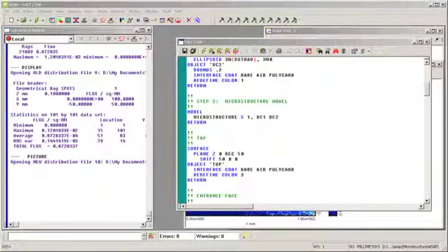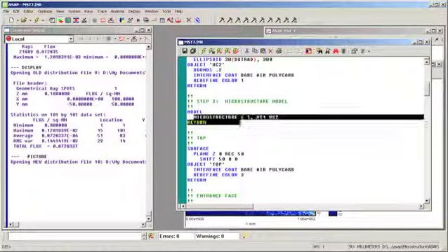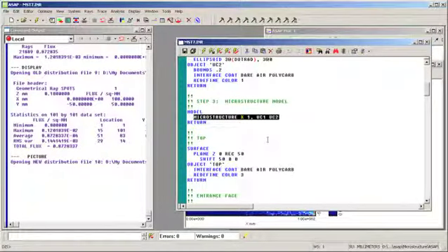Third, we use the new Microstructure command to define a microstructure model under the ASAP model command. Here's the model command that tells ASAP to begin defining models. Then comes the new Microstructure command with several entries. The first entry tells ASAP how to orient the unit cell. In this case, we're defining the reference direction for the local coordinate systems that's parallel to the global x-axis.